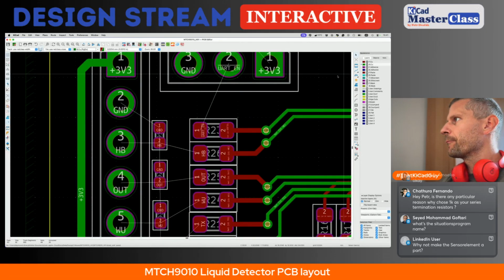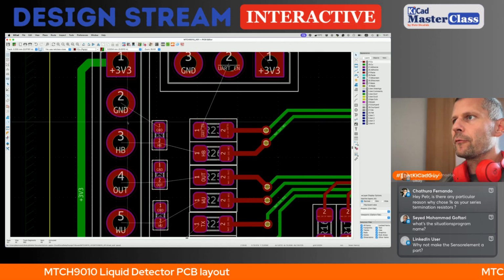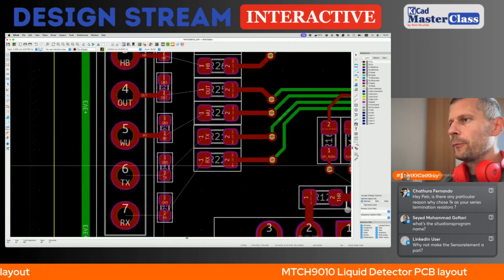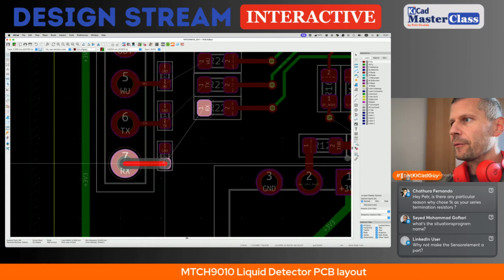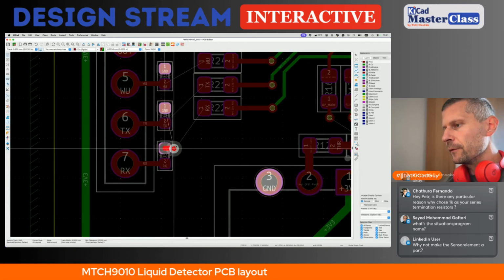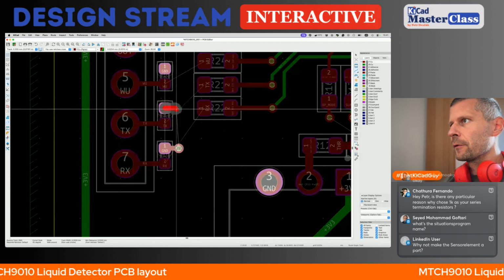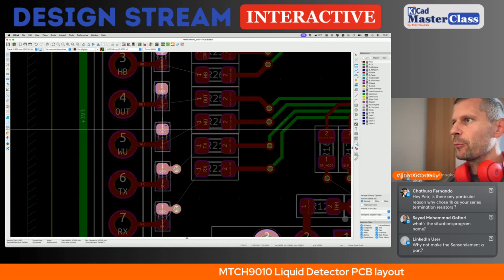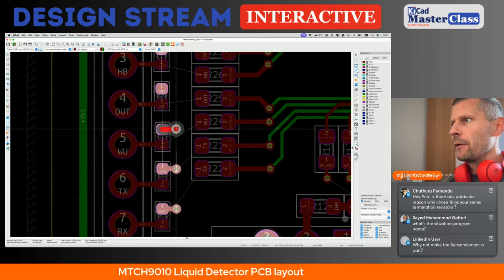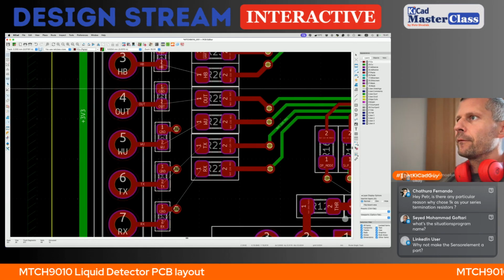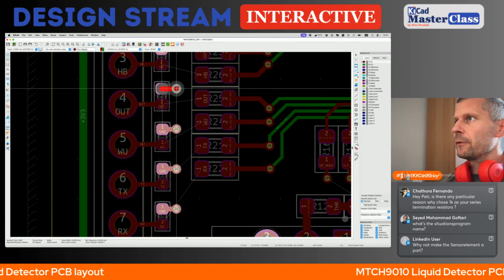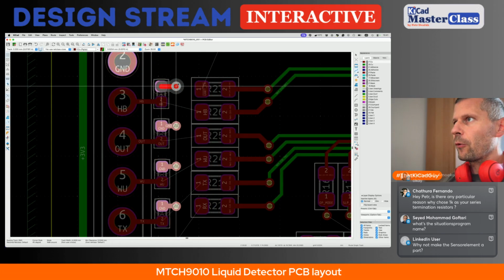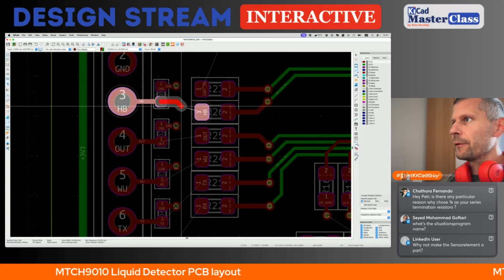Now the top layer interconnection with slightly thicker lines, because we are connecting the pin header, and the thicker the traces are, the better, because this provides firmness to the pin header. It's not so easy to be torn off from the PCB.